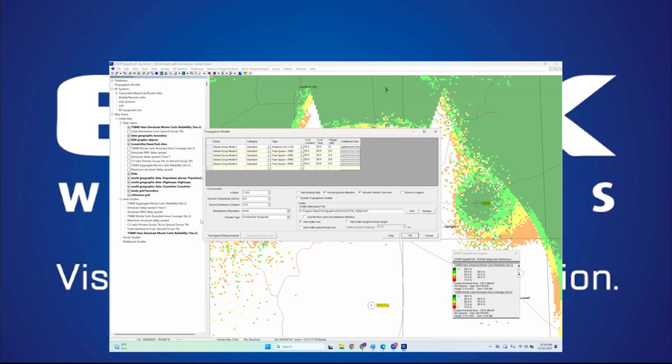then my fading studies should be accurate if those are taking fading into account. However, if I just set up that propagation model targeting the average signal level in the field and run, say, a coverage plot, then I'm not accounting for the potential of fading at all. Maybe my coverage plot with just Anderson 2D at 50/50 might be overly optimistic, especially when we layer in the potential for fading over time and the potential for TDI.